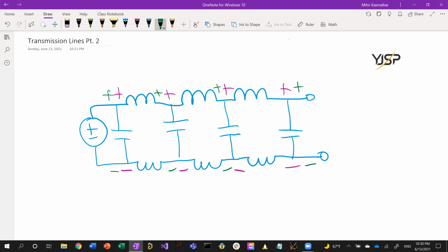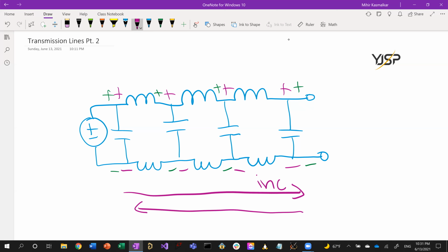in this transmission line. You had this initial wave, which we call the incident wave, which is the initial forward moving wave of voltage and current. And then you have almost another wave that's propagating from the end back to the beginning that's equal to the original wave. This is the reflected wave. It's almost as if that incident wave bounced back from the end of the transmission line, from that open circuit, going back through the transmission line, back to the source, charging everything up again to twice the initial value. And so it's almost like there was a reflection at that point.